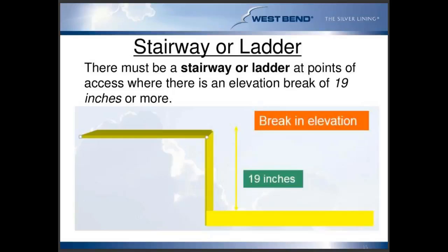But I have been on many roofs over the years where there are different elevations that might be 4 feet higher than the roof being worked on, and there's no ladder in place. There might be a makeshift stairway created by empty pallets. I've seen all sorts of creative ways to address those situations. But long story short, we do need to have a stairway or ladder with those breaks in elevation of 19 inches or greater.